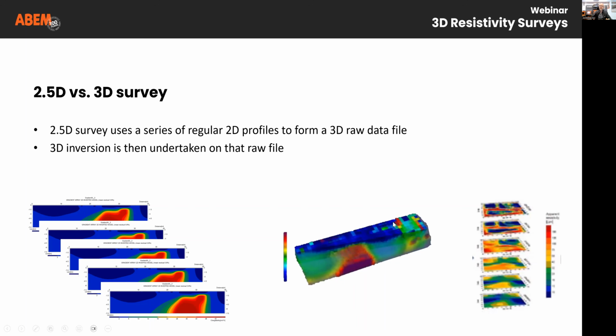And then once we're there, everything from that stage onwards runs the same as a regular true 3D survey. We can use the same inversion parameters. We can then slice the block as we see fit, do thresholding where we remove low or high resistivity values just to leave us with the volume we're interested in.